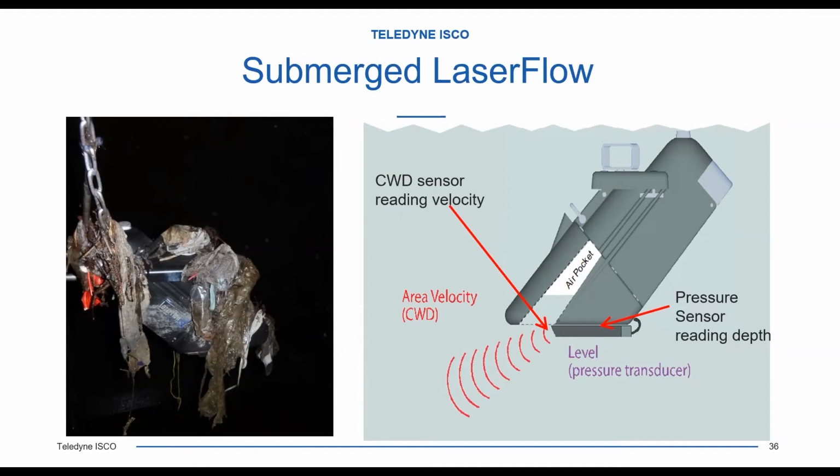It transmits, knows the frequency return, and knows the speed of the water. So now we're able to measure all the way through submergence, and when it comes back out, it will seamlessly transition back to laser. If you have this on an analog output, you can have one continuous analog output that seamlessly transitions from one technology to the other based on the conditions.